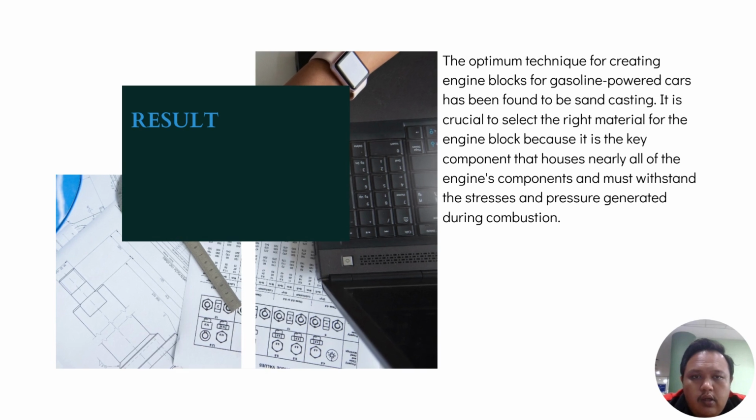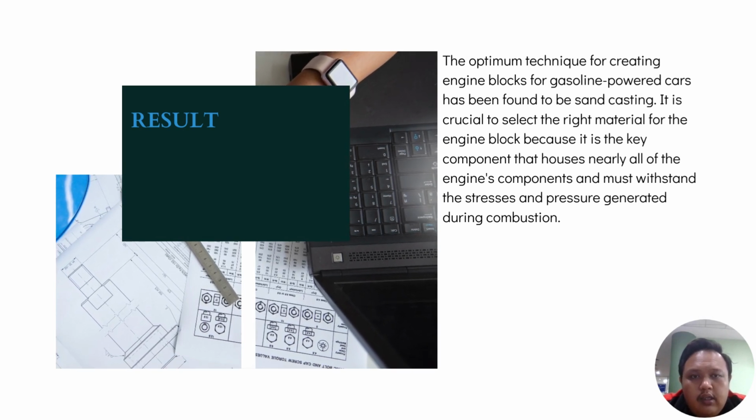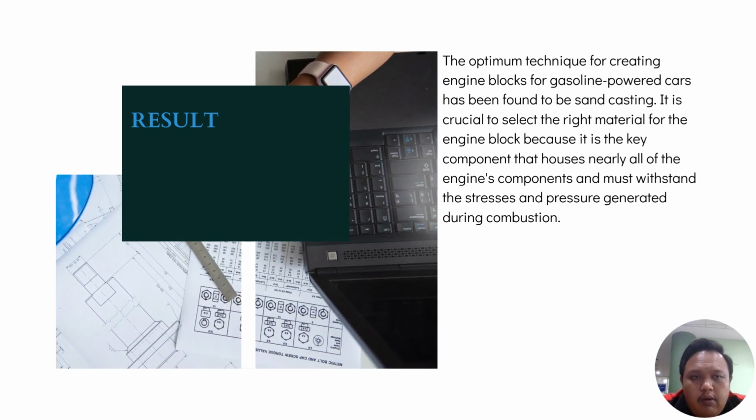So as for the result, the optimum technique for creating an engine block for a gasoline powered car has been found to be sand casting. It is crucial to select the right material for the engine block because it is the key component that houses nearly all of the engine components and must withstand the stress and pressure generated during combustion.